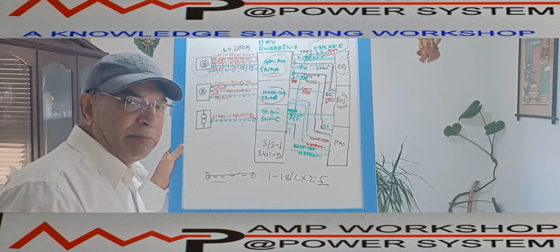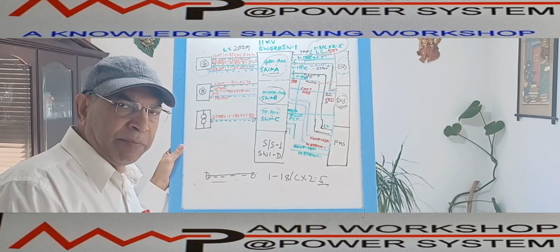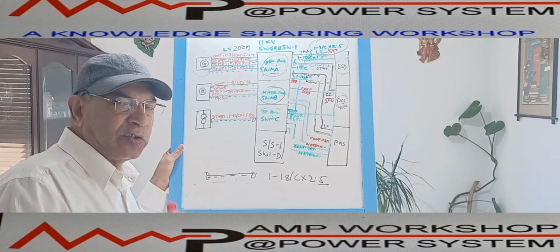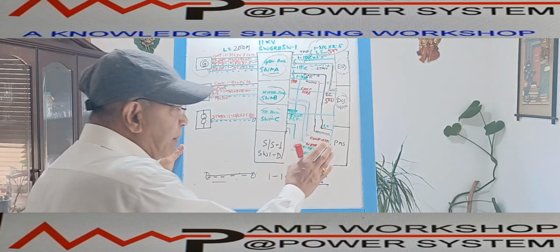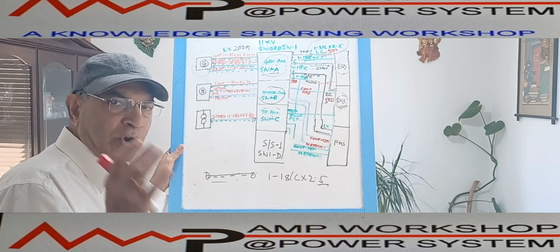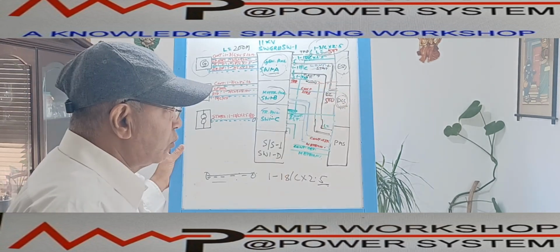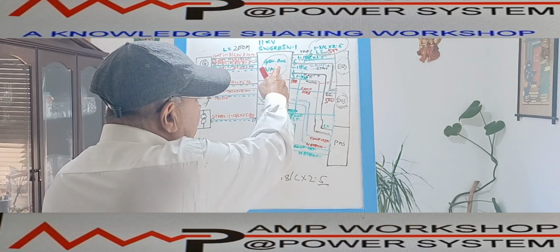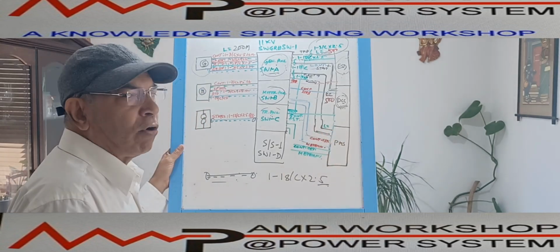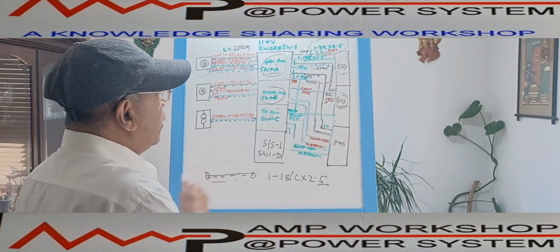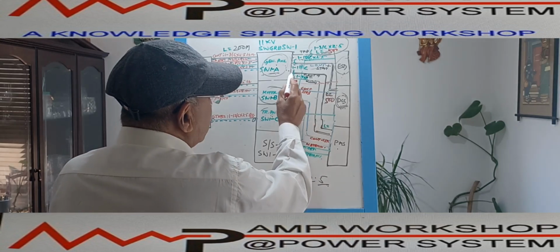In the power management system also, we can open and close the breaker from the power management system, if the power management system is located in the electrical control room or a separate room. In that case, the power management system also monitors the various statuses as we monitor the status in the DCS. So that monitoring and the control of the circuit breaker close and open we also do from the PMS. So there is also one control cable, the same 18-core control cable, between the switchgear and the PMS. That control cable we are showing over here.